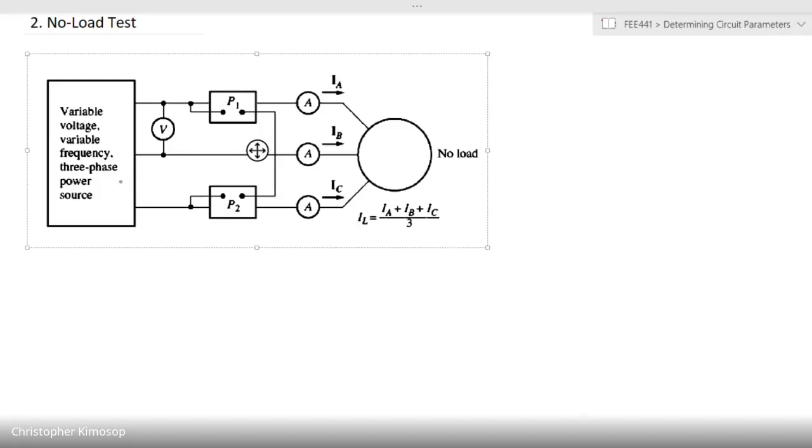When we say no load, we mean that we will run the motor without any load attached to it, so that the only effort the motor has to make is to overcome its own weight. That is the weight of the rotor and the resistance due to magnetizing itself, the losses used to magnetize the rotor, or to transfer power from the supply to mechanical power available at the shaft.